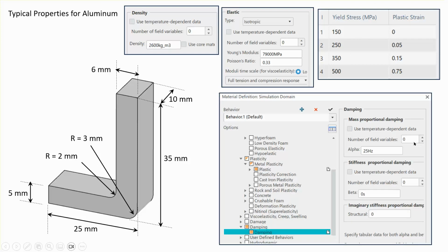And also, the reference that I showed you includes a mass damping coefficient of 25 hertz. The coefficient of structural damping in vibration is the variable alpha, and the units of it are per second, so it is actually hertz. This is the value that I'm using, the same value that the other YouTuber used, and we move on.